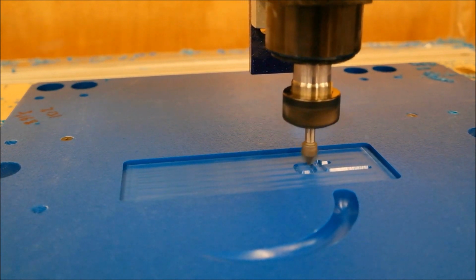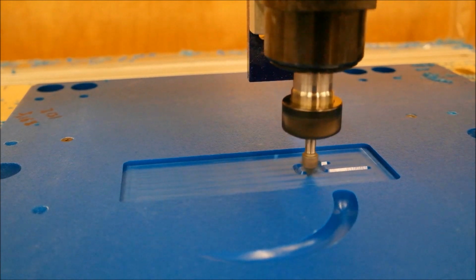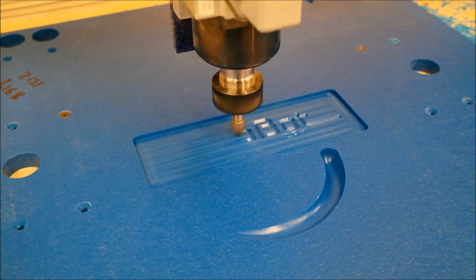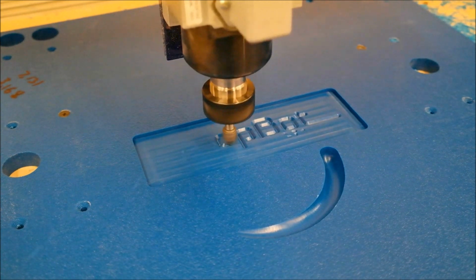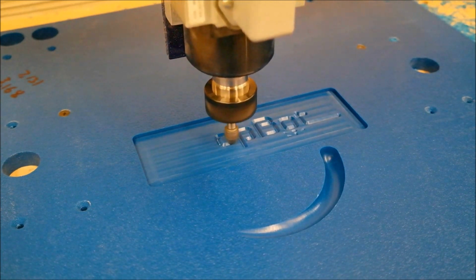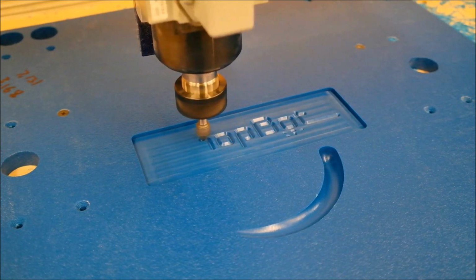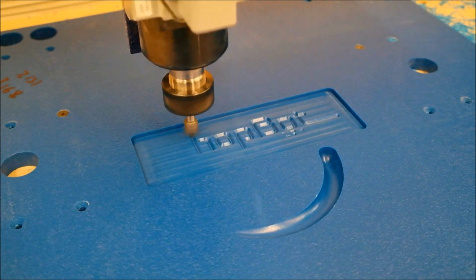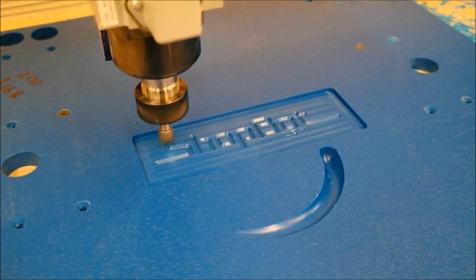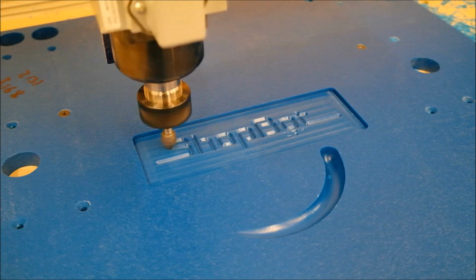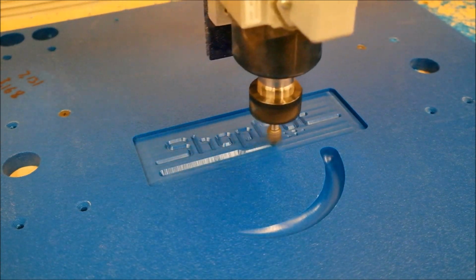You just zero the Z in the same spot as you normally would on the material surface where the file is set up. And here we have a start depth of 0.125. So the machine knows to just cut down in there, and it knows to pick up and move around. So when you're not cutting down inside of that pocket or other pockets, it would pick up and go into the appropriate safe Z height. Really awesome part of the software. Really shallow example right here of the 0.125, but this works on a lot deeper cuts as well.